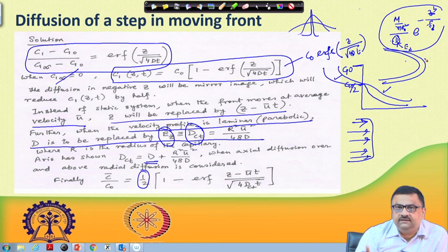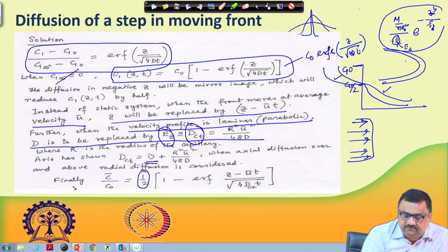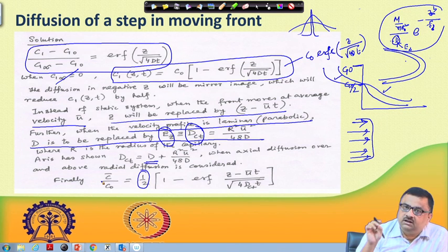That is up to somebody if they want to consider axial diffusion or ignore it; that choice is there. So, now finally, what one ends up with is this C bar. Now, we are calling it C bar. I'm assuming there would be Taylor dispersion inside the capillary. So, Taylor dispersion inside the capillary, only thing is, instead of a Dirac function, I have given a step change. Okay. So, now in that case we had a concentration profile by Taylor dispersion.